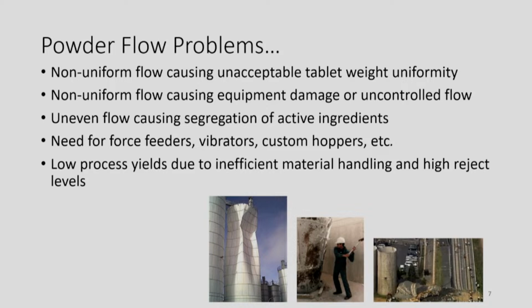Again, powder flow issues, non-uniform flow, tablet weight variation at a smaller level, uneven flow, segregation, etc. So there is a need for other powder flow aid devices like vibration systems, active feeding systems, hoppers, etc.